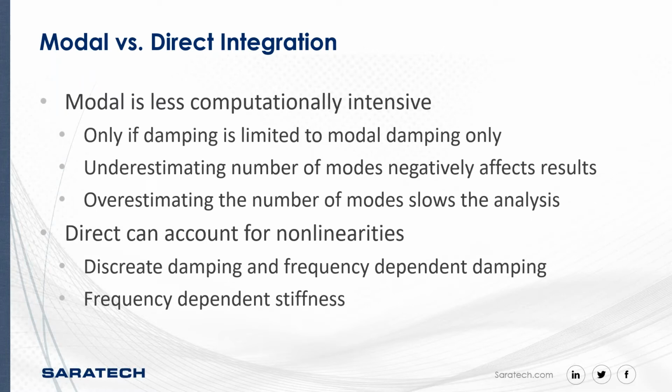The modal is less computationally intense, but that is only if there is modal damping. Any other additional damping effects will slow down the analysis to the point where it's more comparable to a direct integration. There are some other minor issues that you can run into with the modal superposition, and that is that if you underestimate the number of modes that you solve for initially, then you won't get the full application of any sort of important frequencies when you do perform the transient aspect or the frequency response, for example.